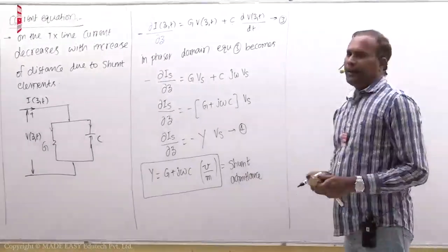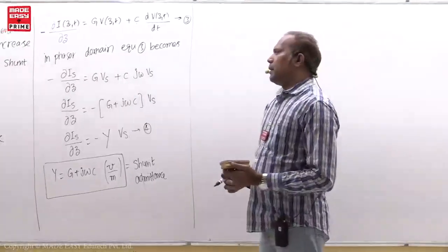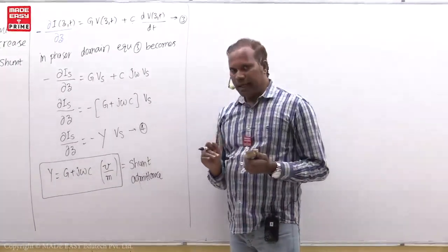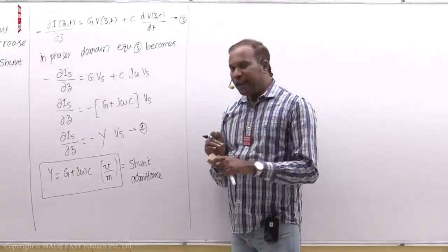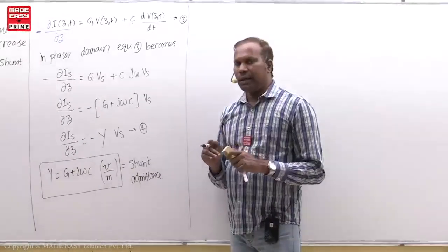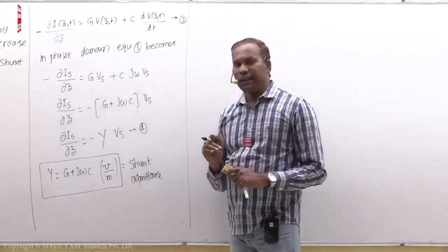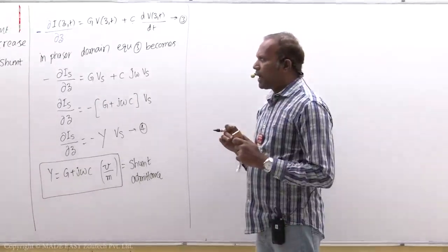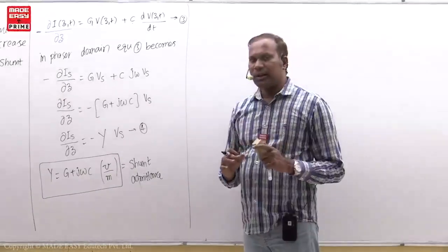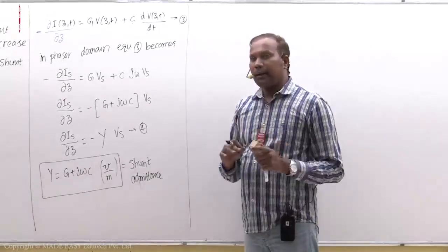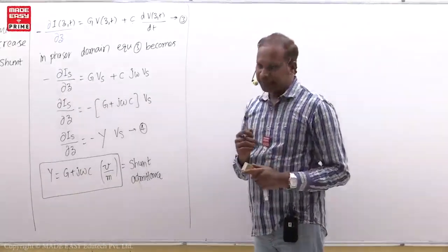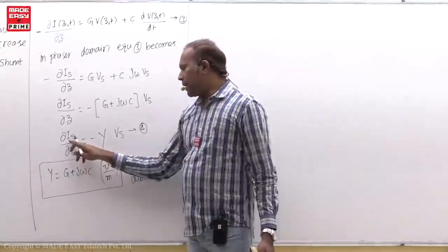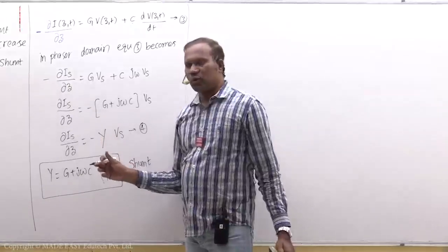If you want the voltage equation of the transmission line, you need one differential equation in which both sides have voltage. If you want the current equation on the transmission line, you need one differential equation in which both sides have current. Here there is one differential equation, but one side has current and the other side voltage, so it is not suitable.